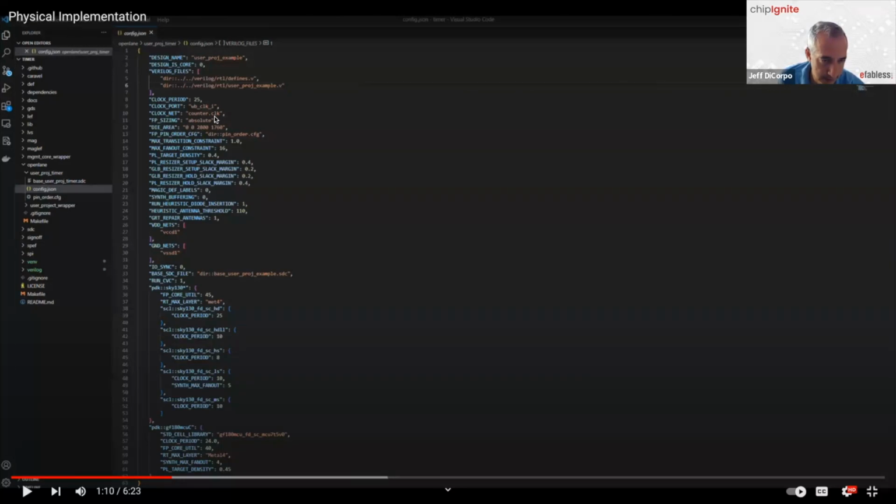If you're doing something where you have timing dependencies that depend on the core clock, but outside of your chip design, there are a number of scenarios where you're going to potentially need to go back and review and update or adjust the constraints file, depending on the specifics of your implementation. We can probably do a follow-up on that, because there's a little more of a conversation around when that happens. But for these simple designs that you're seeing here, the constraints file does not need to be updated and can be run as is with just some simple modifications, which we'll show you in this video.